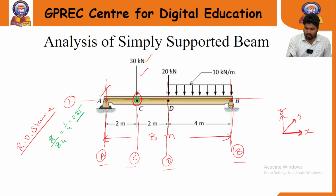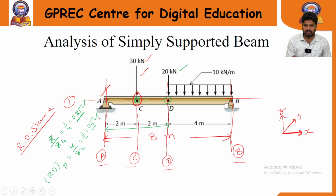C. If you want to apply the 20 kilonewton load at point D, you need to calculate the relative distance at point D. What is the total distance from A to D? From A to D we have 4 meters. And what is the total length of the beam? 8 meters. Then the relative distance for point D is 0.5. By giving these relative distance values, you can apply the 30 kilonewton load and the 20 kilonewton load. So this is how you need to calculate the relative distance.